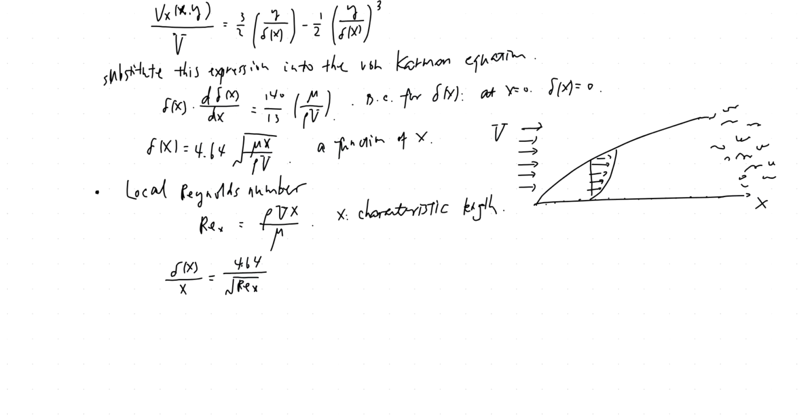The left-hand side is the boundary layer thickness versus the distance, so it tells you how this proportion changes with Reynolds number. And for this particular geometry, for this boundary layer problem, the transition to turbulence typically occurs when the local Reynolds number is larger than 10 to the fifth. It's important that this is just for this problem. Different problems would have different Reynolds number transition regions.